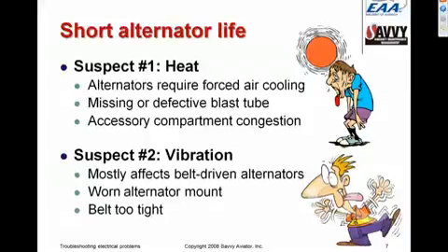And if the blast tube is not present or is not positioned correctly to be blowing copious amounts of cold air on the back of the alternator, it will overheat, particularly the rectifier assembly in the alternator, and will not live very long. So if you're going through a lot of alternators, that's one of the things you want to check, particularly if your alternators are mounted in the rear part of the engine compartment as opposed to right up front in the air blast. The second big culprit is vibration.